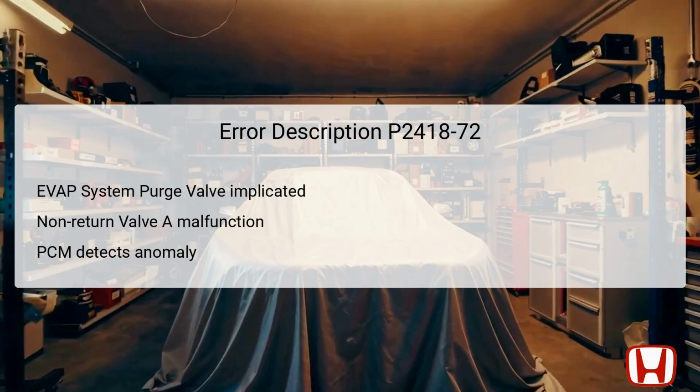DTC P2418-72 indicates a malfunction related to the evaporative emission EVAP system. The EVAP system helps capture and recycle fuel vapors from the fuel tank. The specific component at fault is the purge line non-return valve A, which is part of the EVAP canister purge valve assembly. This valve's role is to prevent the backflow of fuel vapors into the fuel tank from the purge line, thus maintaining proper system pressure.